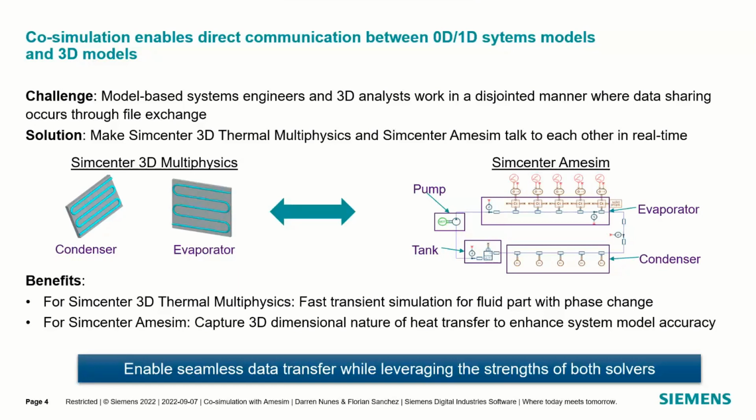And as I mentioned before, with AIMSIM, there are different levels of fidelity, different ways of modeling. So if you see, there are these boxes that are part of that subsystem that you saw on the previous slide, where we have the pump, and we maybe have different commands or controller logic going into that pump. We discretize the evaporator over 5 different sections, as well as the condenser.